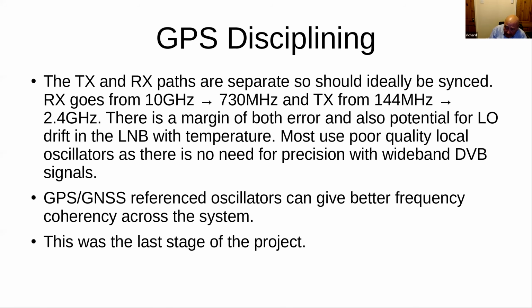So because you're running at 10 gigahertz, it's quite a good idea to try to use this GPS discipline. Basically, you have an accurate reference frequency that you use to synchronize the various parts of the transmit and receive chains.